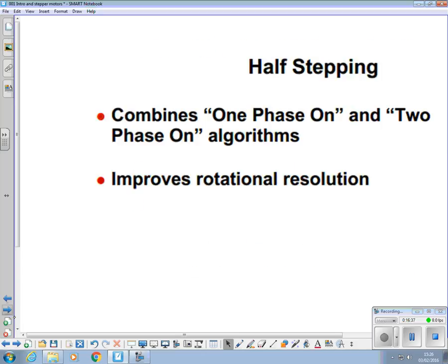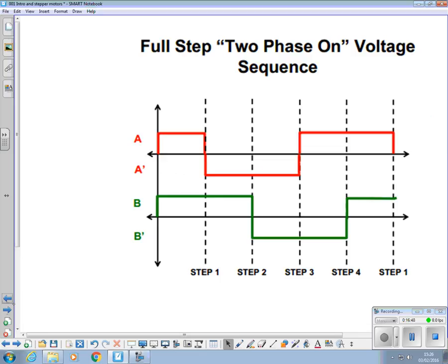It's effectively going to increase the amount of torque that you've got for that motor, because you've always got 2 coils energized, and even when one turns off, the other one's still energized. So overall, you're going to get more torque out of that motor by switching it in that way, because you've got 2 coils energized.